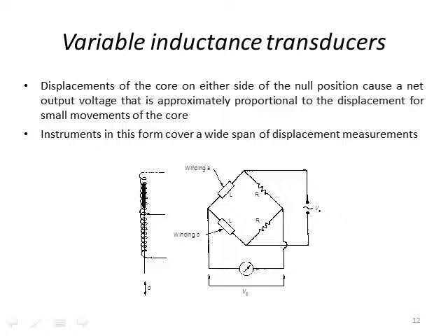So all of these sensors are very, very similar in the way that you detect this movement, and these displacement sensors, when you're doing it electronically with a capacitor or an inductor, it's very useful to put this into a bridge configuration, because in the null position where you don't have any displacement, you can always tune the output voltage to be 0.